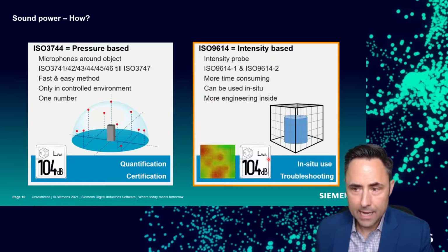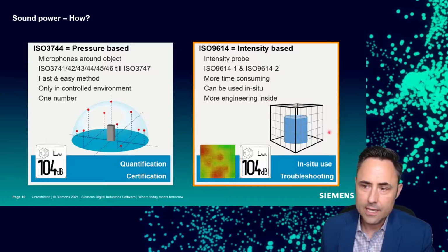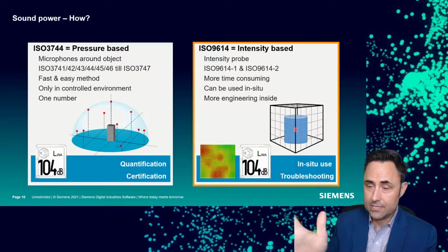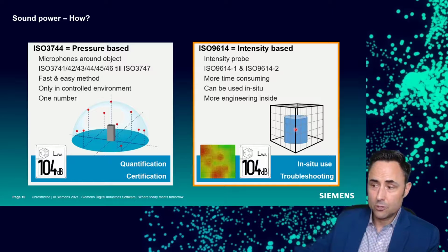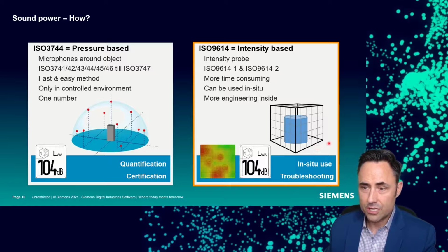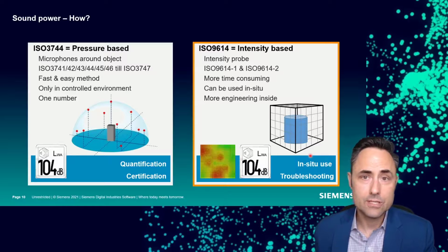So how do we get to sound power? Well, we're measuring the intensity. We know that it's watts per meter squared. So we end up having to surround our object under test in this wire mesh. This is our test surface. This is how we're going to ensure that we test at a certain distance away from our sound source, and then we test over a certain area. This mesh creates our area. Then we take the sound intensity, or watts per meter squared, that we measure, multiply by this surface area, and that's how we get to our sound power.